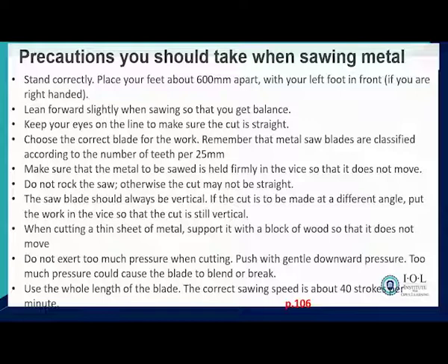Right? If you are cutting a thin sheet of metal, you support it with a block of wood so that it doesn't move. Do not exert or put too much pressure when cutting. You should just be gentle. Otherwise, if you put too much pressure, the blade may break. When you are cutting, you need to use the whole length of the blade. Do not use only the center part. Otherwise, your blade will get finished on one part. So you need to use the whole blade.